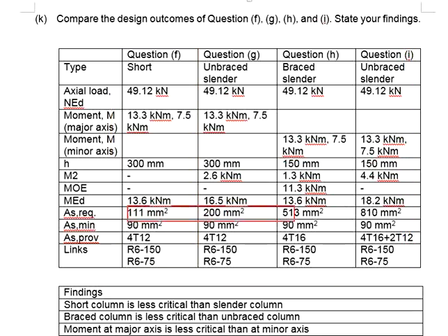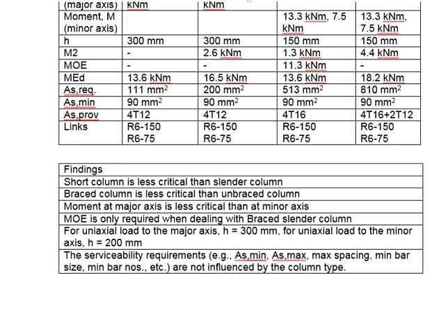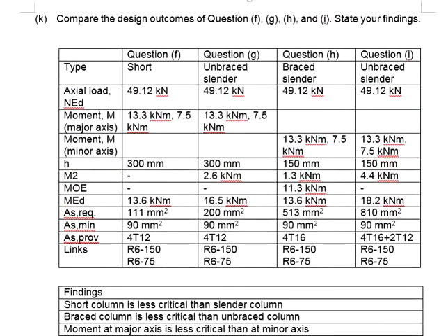In terms of the amount of reinforcement bar required, slender columns always require more reinforcement, even with the same amount of loading acting onto the column. This gives you a good understanding when it comes to the design of the column. If you intend to make the design more economical, you can consider manipulating the slenderness of the column.